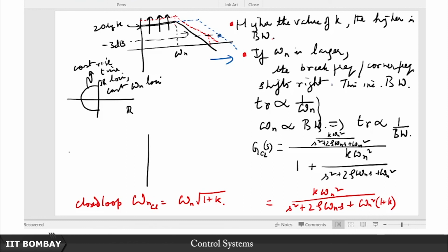This is the only case where I am considering a Bode plot of the closed loop transfer function. This is the one off, so don't go about thinking that this is general. In general the Bode plot is drawn for the open loop transfer function and all the information is gleaned from there.